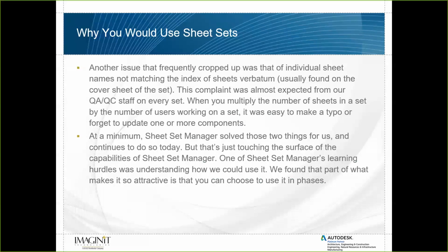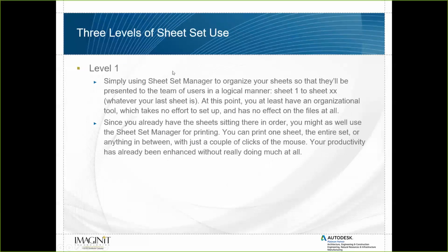One of the sheet set manager's learning hurdles was understanding how we could use it, and we found that part of what makes it so attractive is that you can use it in phases. So what we're going to talk about are the 3 phases of sheet sets. Level 1 is simply using the sheet set manager to organize your sheets so they'll be presented to the team of users in a logical manner, sheet 1 to sheet XX, whatever your last sheet is. At this point, you at least have an organizational tool which takes no effort to set up and has no effect on the files at all.